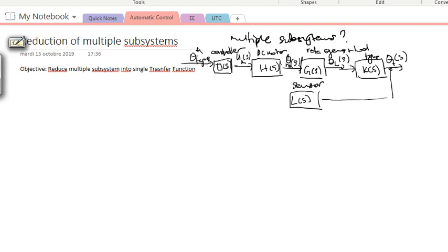So it takes the measure of theta T, and then it translates it into a certain signal, and then the signal is compared with our input, right? So to calculate the error, and then the error is injected back into the controller.